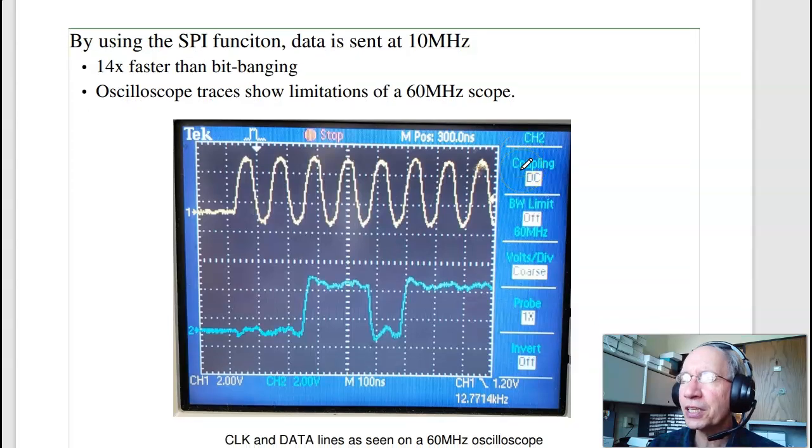What the data looks like on my oscilloscope is this is kind of pushing my board. I've got some capacitance. That's a square wave with some capacitance on my wires. This is the data. It is getting through, but that's kind of pushing the limit.